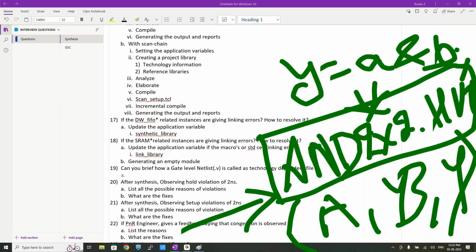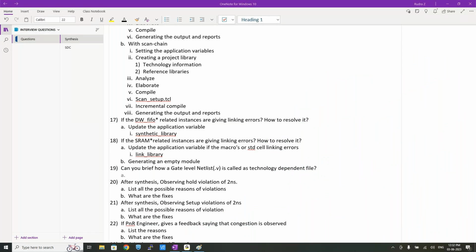Okay. So, the reason I'm going to tell you is during the optimization stage, based on the timing violations generated in the design, it is going to optimize it, right? That means for timing analysis, the cell delays are required, the parasitic information is required, correct? So that varies with respect to technology, and also based on the vendor providing it, there might be changes with respect to the cell namings also.